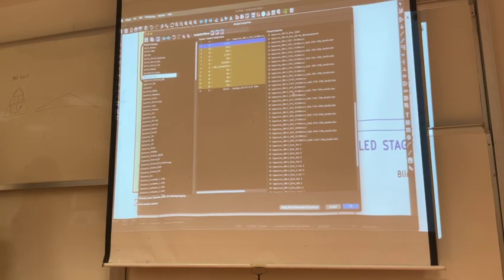1206 is in mils, like American measuring units. And it says the metric version right next to it. It's all standard for the assembly components. It is the size of it, really. 1206 is large. 0603 is smaller. I suggest this one for hand soldering. It makes the pads larger. So what is a pad? It is the copper that is visible to you.